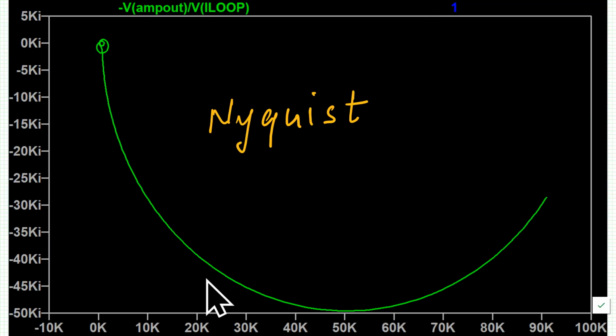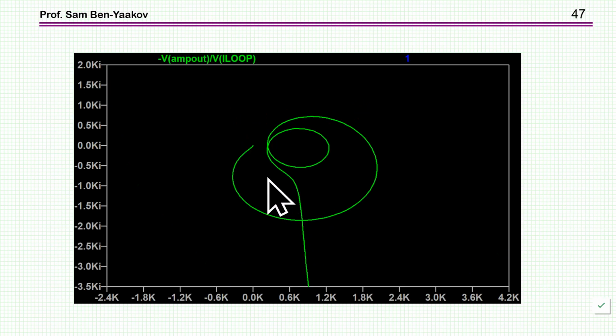So here is the Nyquist. Now the crucial point is here, the -1, 0. You can't see it because the scale is just too high. It's a high gain here. So I'm zooming here, and here is what you see, where there is a lot of encircling here, but you are not encircling this point. I'm going to zoom later on to see it closer. So from the point of view of stability, there is no problem, okay?